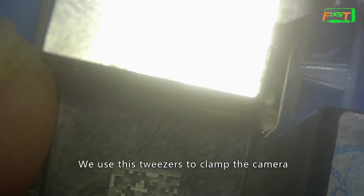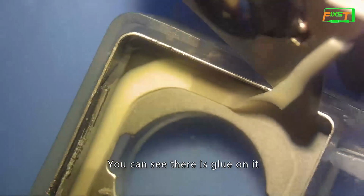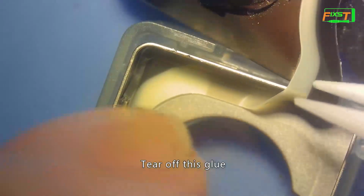We use these tweezers to clamp the camera. You can see there is glue on it. This is why we need to heat up. Tear off this glue. After removing this glue, you can remove this glue, in case it affects the focus. After removing it, we can apply some glue when we install it.